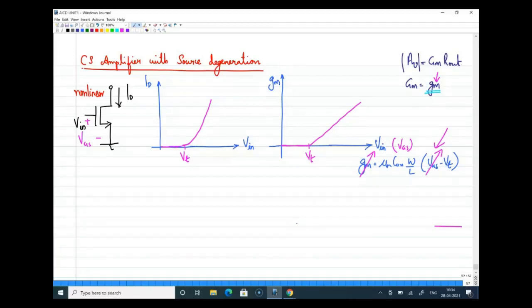Now, when your voltage varies, your GM is also varying, and your gain is varying, right? So, as I mentioned, if we are looking for a variable voltage, variable amplifier, this is perfectly fine. But otherwise, this is not fine, because gain is something which should be constant. It should not be varying, right? I think you will agree to that.